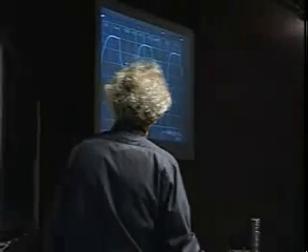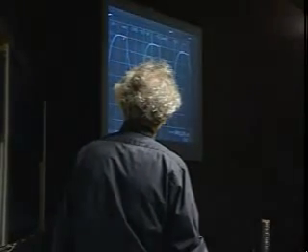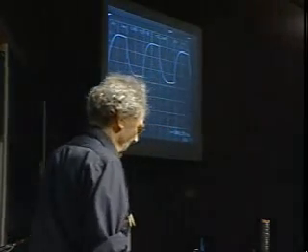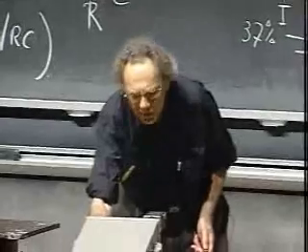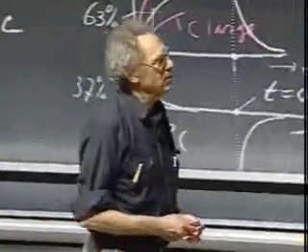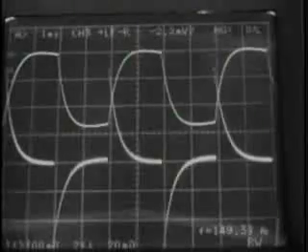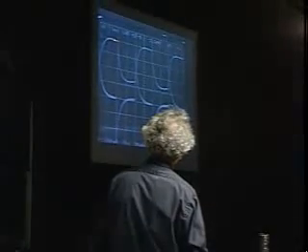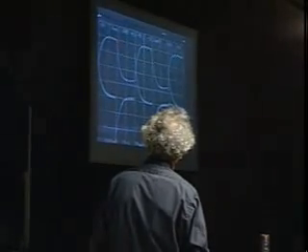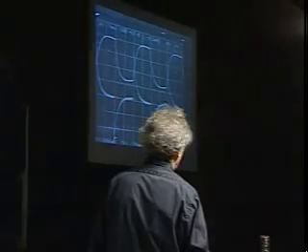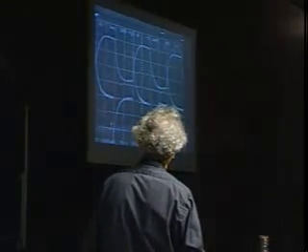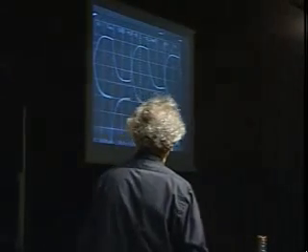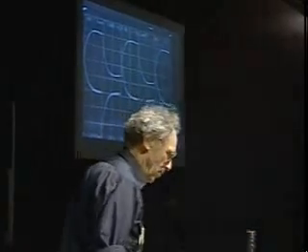And then here, I'm going to switch it back to position 2, and you see it's discharging. And then it's charging up again and discharging. And now I can also show you the current. You see it on the same plot. As the capacitor is charging, the current is high. But by the time that the capacitor is fully charged, the current is 0. But the moment that I throw the switch to position 2, the current flips direction, becomes negative, and then as the capacitor discharges and heat is dissipated in the resistor, ultimately the current again will become 0.